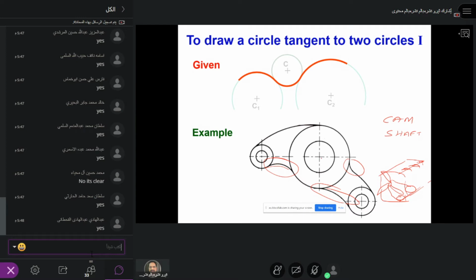So this camshaft is continuously rotating, and there's a rocker arm here, and this rocker arm keeps on pushing the valves inside the engine so that the valve can open and close such that the engine will keep on running. So it's an extremely important mechanical component that you should know how to make.